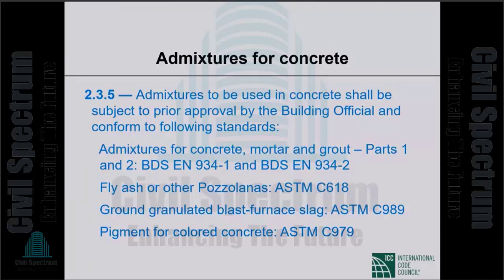Fly ash or other pozzolans will not be called admixture today. It's mineral admixture now, supplemental cementitious material. You have already seen the spec is C618. Ground granulated blast furnace slag, that is also cementitious material, ASTM C989. Pigment for colored concrete, C979. BNBC cites those under admixtures for concrete.